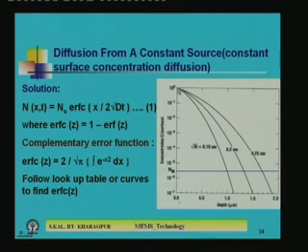So, there is continuous supply, and the surface concentration will be constant at the surface. Then if you increase temperature and time, t is the time and D is the diffusion constant, which is a function of temperature. So, the total deciding factor is the D and t product.